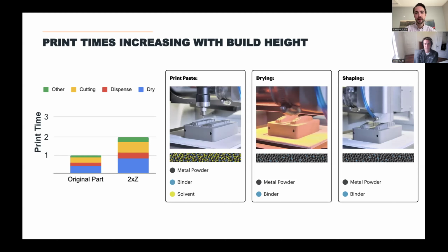Suppose you have flexibility in the way your mold frame is designed. You could also shim the bottom of the insert up in the mold base to ensure that the parting line's consistent, and the mold frame accommodates a new design to reduce the part height. So this is a pretty powerful lever for influencing piece cost and throughput.